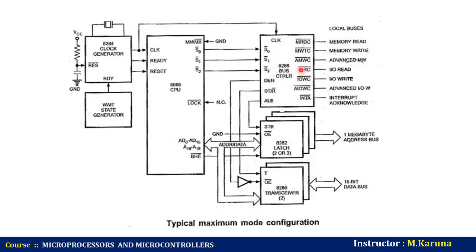It derives the outputs ALE, data enable, data transmit or receive, memory read command, memory write command, advanced memory write command, IO read command, IO write command, advanced IO write command. In case of maximum mode, memory read command, memory write command signals are used as memory